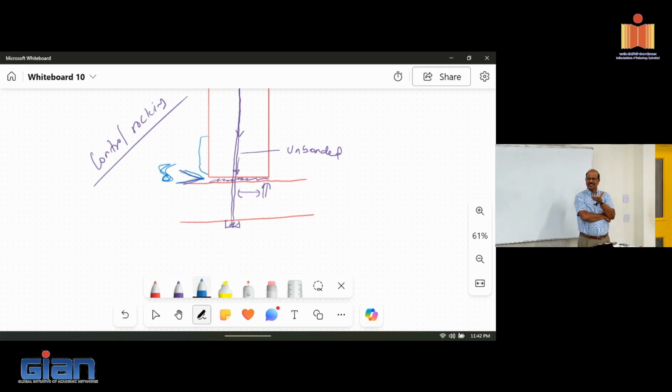But the anchorage is a key piece, which we discussed. You could partially bond it. Go ahead, Satish. Yeah, you just mentioned keeping the strand elastic all the time. But at the same time, this strand would also help in the moment resistance. Yeah, of course. Keeping the strand elastic is not difficult if you keep the whole thing unbonded, because your strain gets distributed.